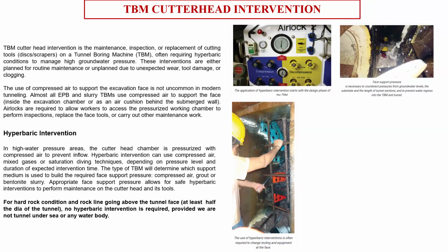So what we do is check the stepping. Sometimes, due to out of tolerance, there can be stepping. Stepping means that between two segments you find an offset. The offset also has a certain amount of tolerance. It can be 5 mm, 6 mm, or 10 mm. If the out of tolerance in the stepping is too much, then at the junction of the two segments we do some additional grouting, or some epoxy filling, so that the junction is waterproof.